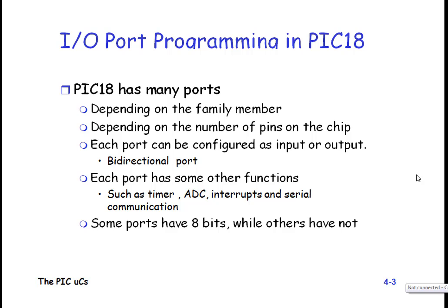So PIC18 has many ports. It depends on the family of members, and also on the number of pins on the chip. Each port can be configured as an input or output, like bidirectional ports. Each port also has other functions, like timers, clocks, ADC, interrupts, and serial communication. So there are different types of ports, mentioned in four points.